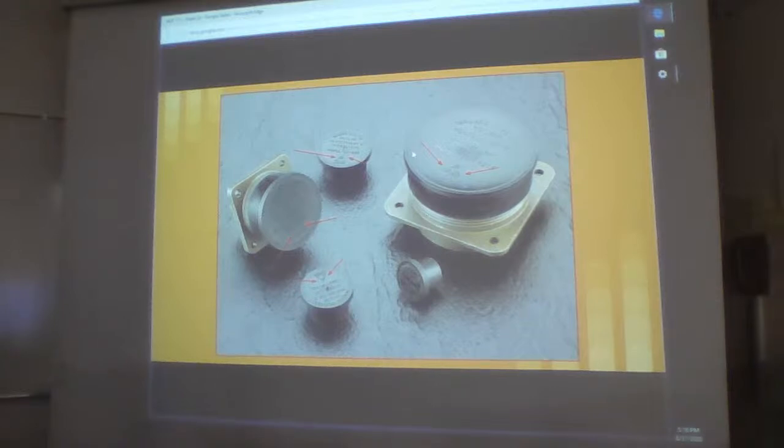So the problem with that, if we touch the mating pins, the electrostatic discharge that builds up, the electrons that build up from us all day walking around on carpet and touching door handles and all of that, if we touch the mating pins of these components that have these connectors, we could be sending a transfer of electrons through electrostatic discharge, and we could be damaging internal components of that machinery that could cause damage that we might not even know. And that's not good.